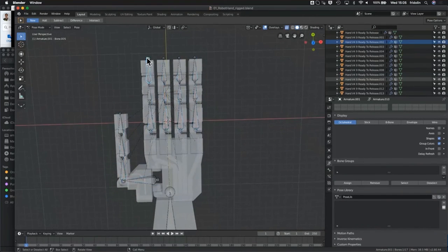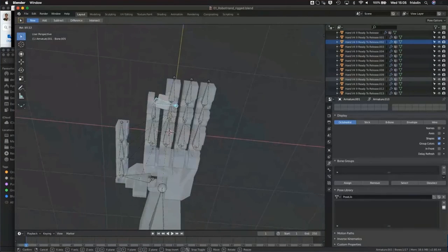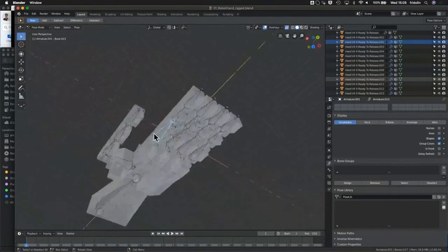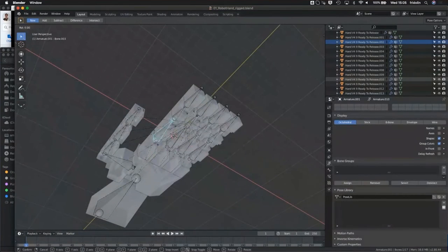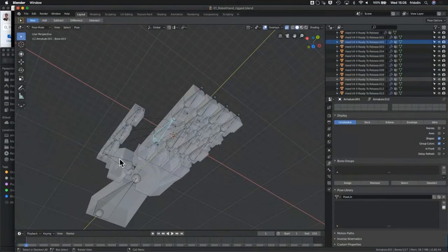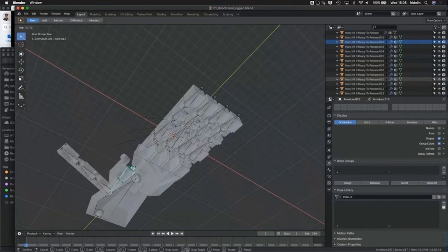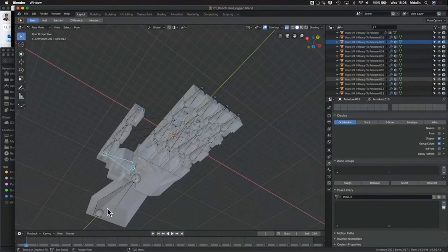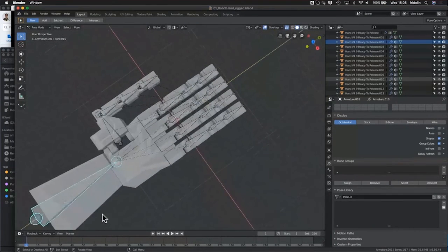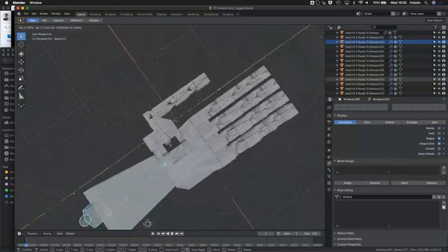And what happens then, instead of object mode and edit mode, if we've got an armature selected, we can also go into a third one called pose mode, which you see here, which means that now we can grab a given bone and move it around. And if we work with a lower down bone, then it moves the ones above it. They move with it. So this is the benefit of working with an armature, and they're all connected together. If we take the wrist bone and move that, the whole thing moves with it.